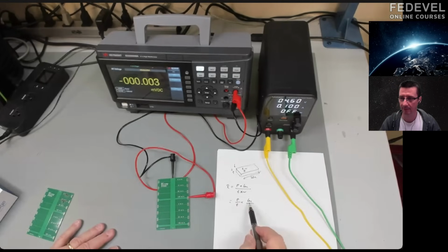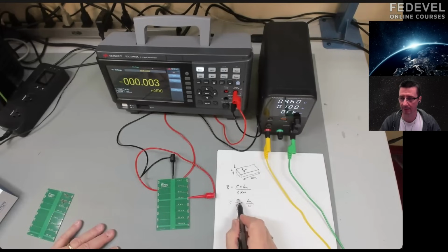And so you tell this number is fixed. It's the same bulk resistance, same thickness. You tell me what the length of the trace is and the width, and I'll tell you what the resistance of that trace is. And the reason I wrote it this way is because this is a special term, because it's the same for every single trace we draw on that layer. We're going to pull that out and we're going to give it a special name.